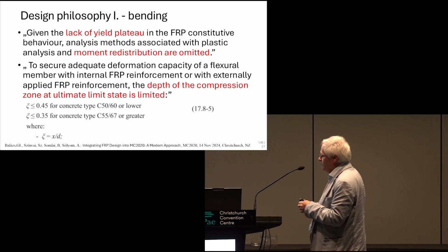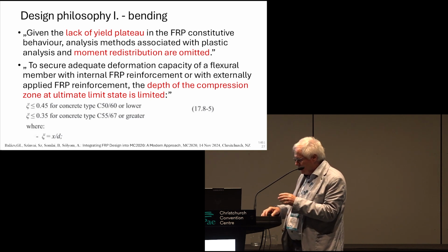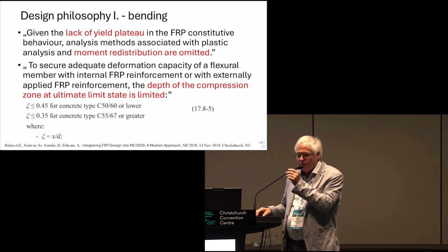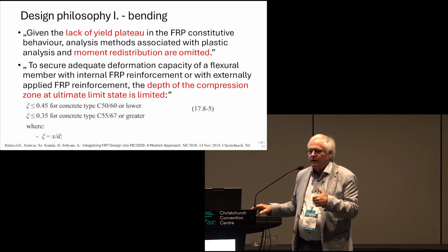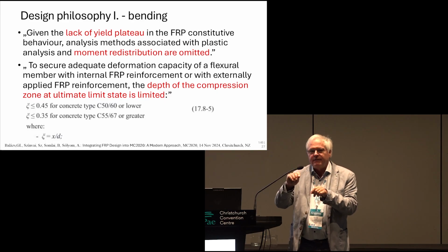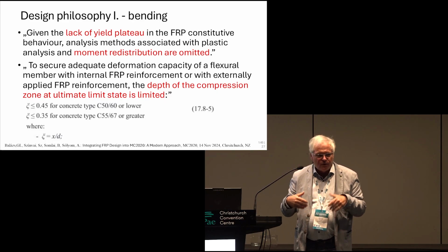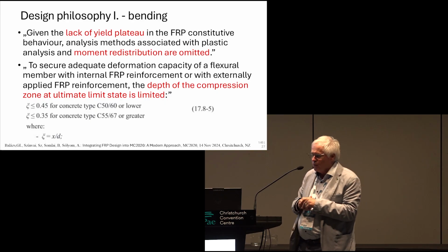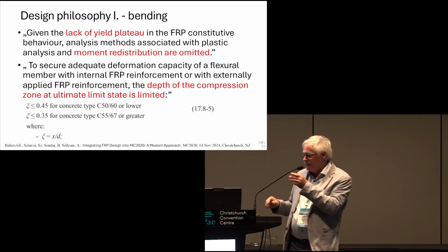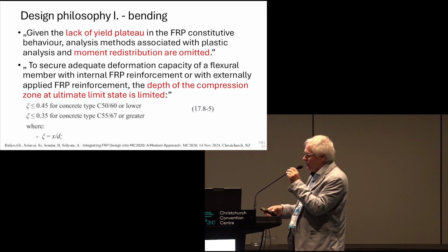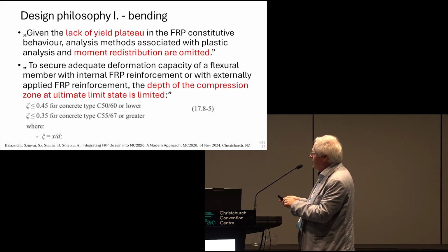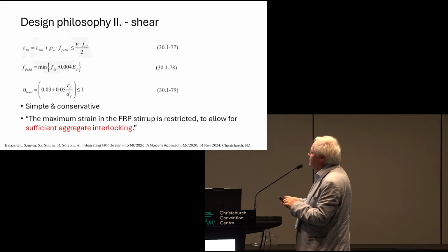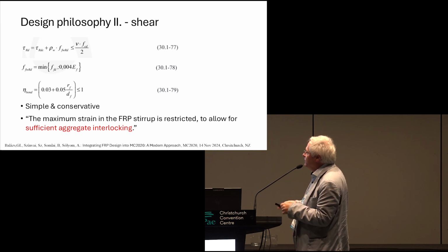We know that, and this is very important, if we speak about design philosophy, we have to see concrete failure and not FRP failure, since FRP is linear, elastic, and brittle. So the failure philosophy in the Model Code 2020 is to avoid failure of FRP and to have concrete failure, and this is the way that we can regulate it.